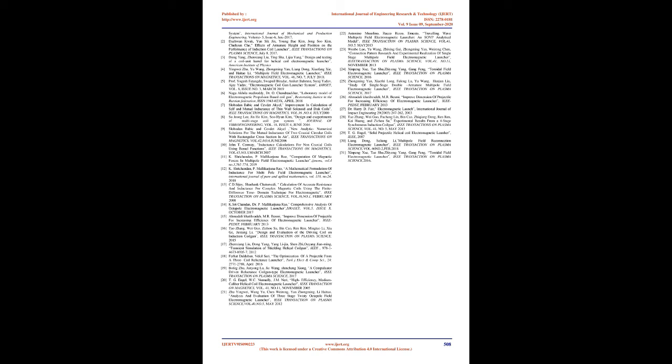The author proposes a toroidal field electromagnetic launcher with a new accelerator mode to avoid the catapult coil. It utilizes a toroidal magnetic field interacting with radial current to generate axial accelerating force, which avoids the catapult coil for initial launch speed. The toroidal magnetic field interacts with radial eddy current to produce axial acceleration force. Without the catapult coil, the launcher has great axial acceleration force.